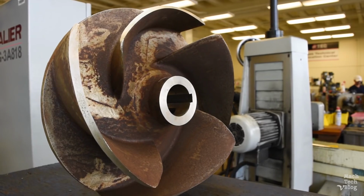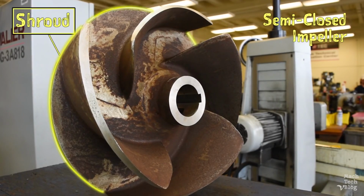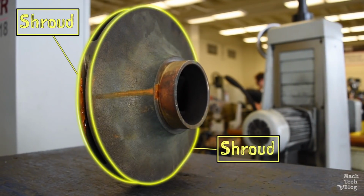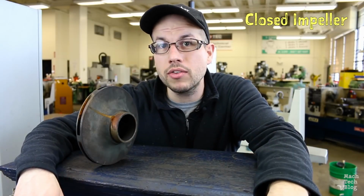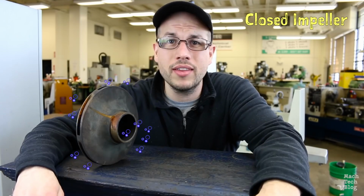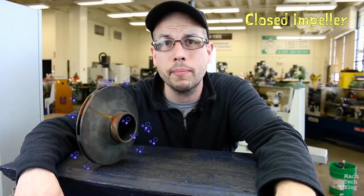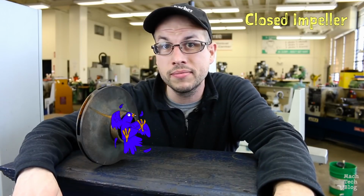If the vanes are mounted on a backing plate called a shroud, then the impeller is a semi-closed impeller. And if the vanes are sandwiched between 2 shrouds, then it's a closed impeller. Closed impellers are more efficient than either semi-closed or open impellers because the fluid is directed through very well-defined pathways. That means that more of the fluid is pumped out into the system and less of it is just recirculated around and around inside of the pump. Of course, the trade-off is that they can very easily get clogged with debris.